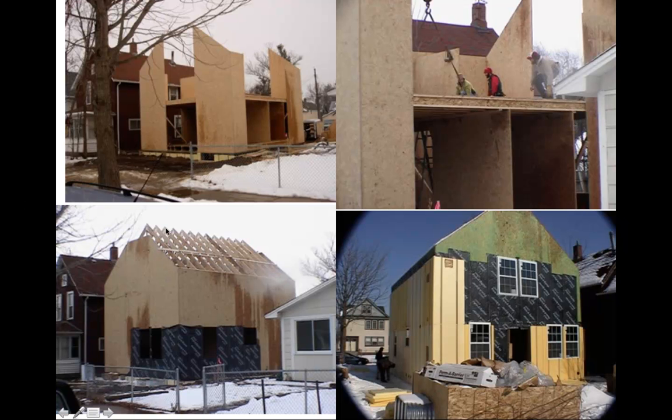So you have the loads coming down from the roof and from the snow load that's going to be supported by the column over this whole length. Well, if you think about a fairly narrow column over this whole length, that's going to be much more difficult, and it's going to be a much too long a buckling distance.